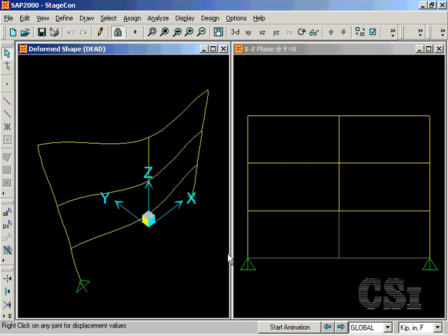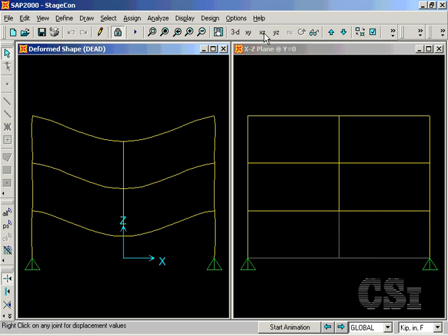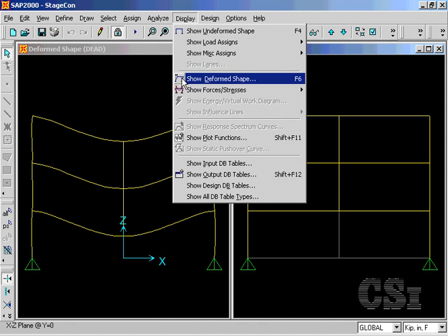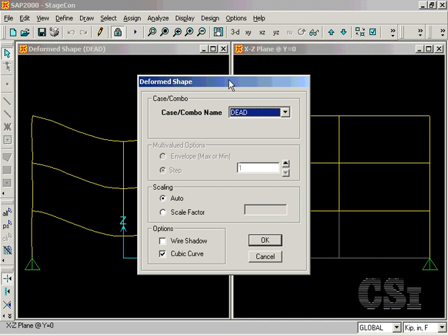Change the 3D view to an elevation view with the dead load case displayed. In the right window, we will display the deformed shape from the staged analysis cases to see the effect that this loading approach has on the building. We start with Stage 1 and Step 10, which is the last step. Set the scale factor to 50 to match the scale on the left.